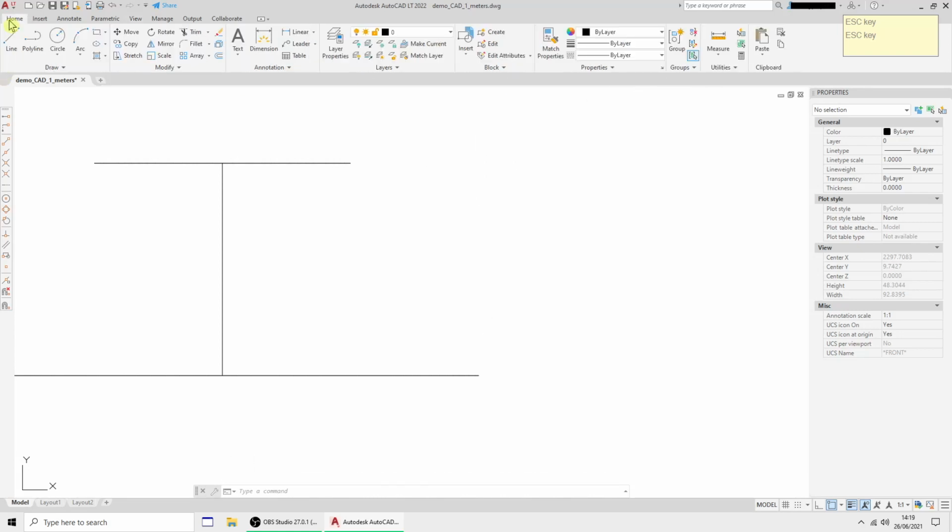And this is important to remember, because when you come to drawing things and measuring things and you've got 3D Z values, they can really throw you out. Basically what I was doing was measuring from there to there, which should be 15, but because I was locking onto this line, it was pulling it down and measuring like that.